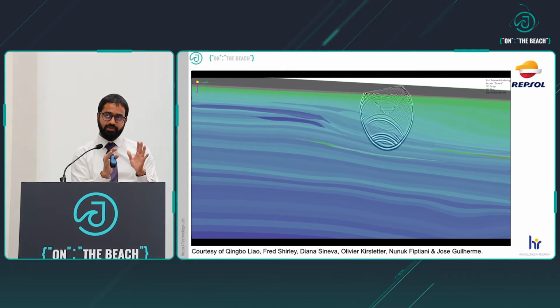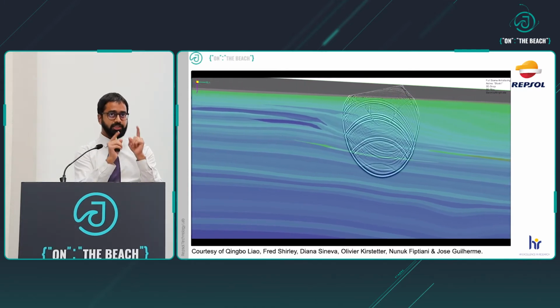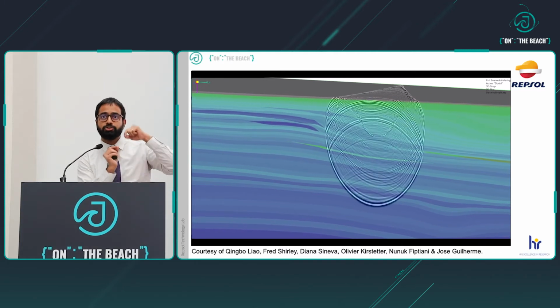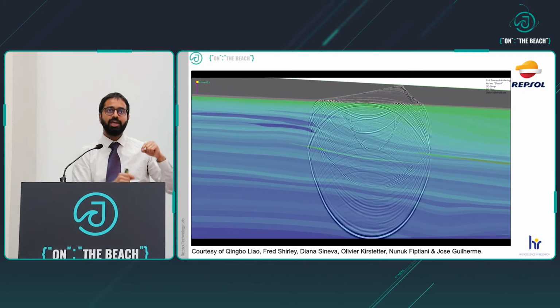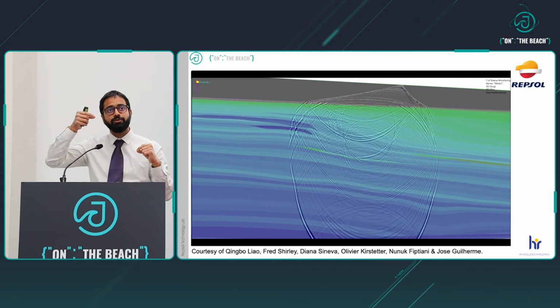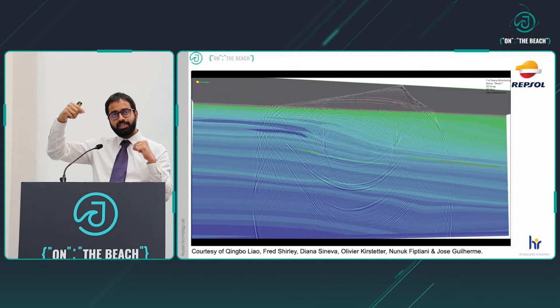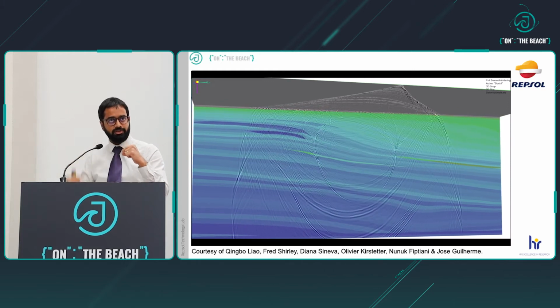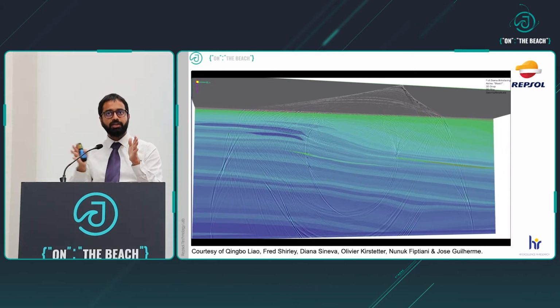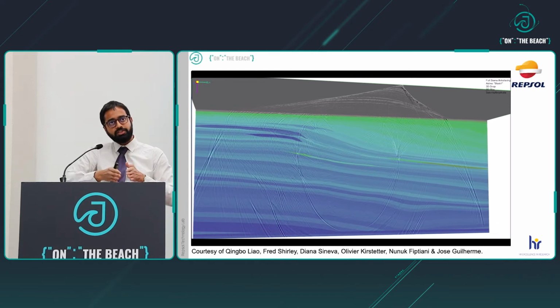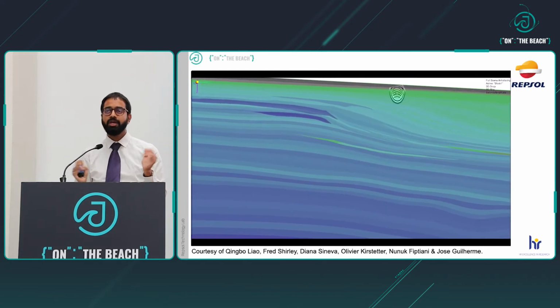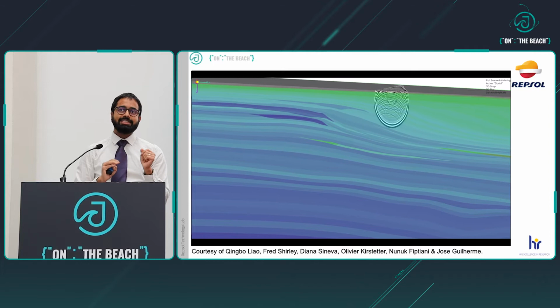So you have large data gaps, and it's important to remember that these data gaps are trace-wise. Okay, it can also happen that the geophone stops working after some time. So that would be gaps inside the time series, but we will be looking at gaps which occur because the traces disappear. Okay, so that's the problem.